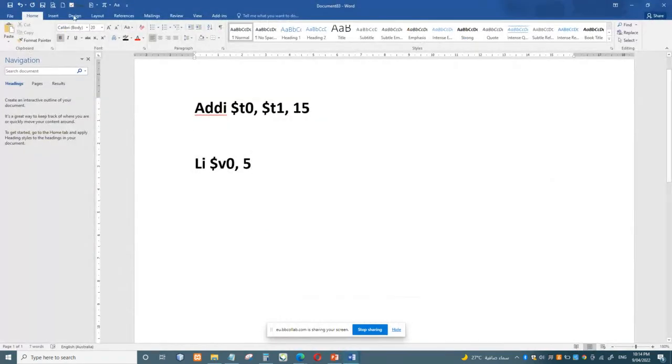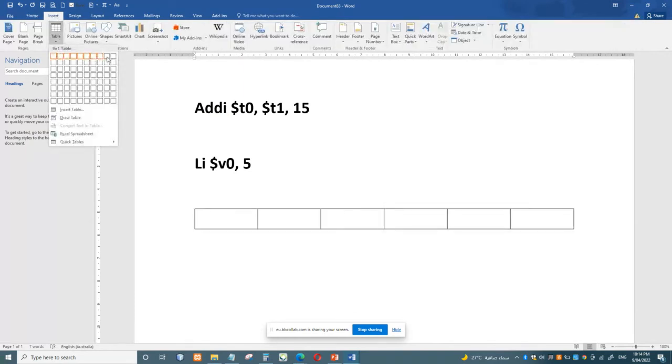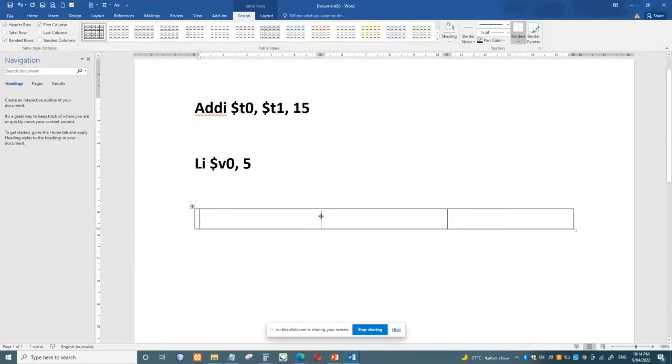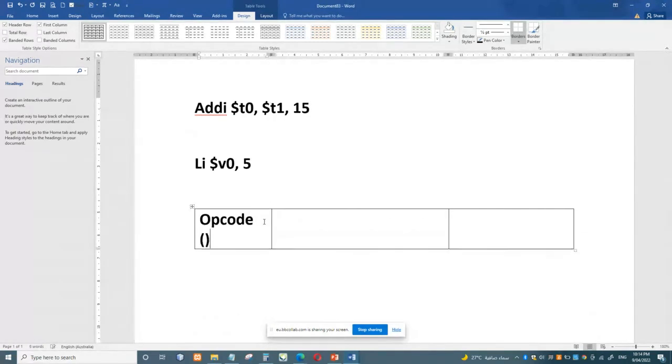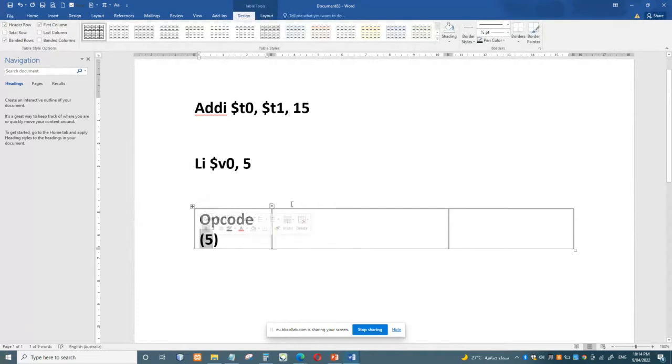Again, say for example, you make an instruction table. If this is your total instruction, and this is your opcode, and if the opcode requires, say, 4 bits or 5 bits, then this opcode, li, is our opcode. We can use 5 bits because the size of your total instruction is 16 bits.